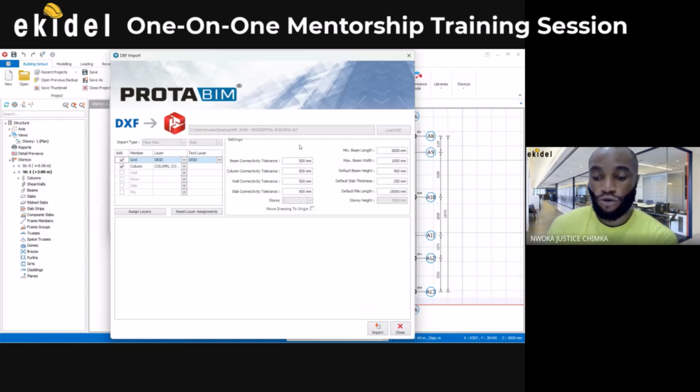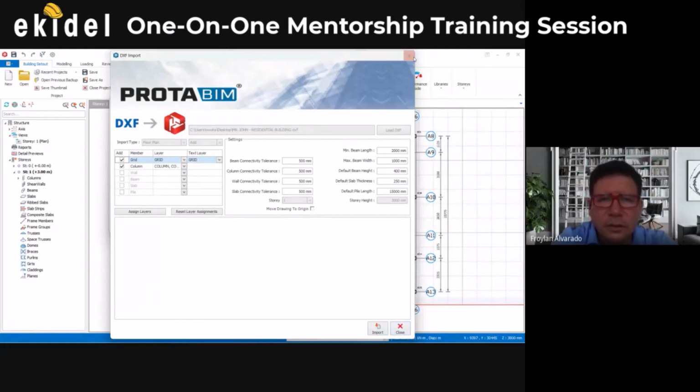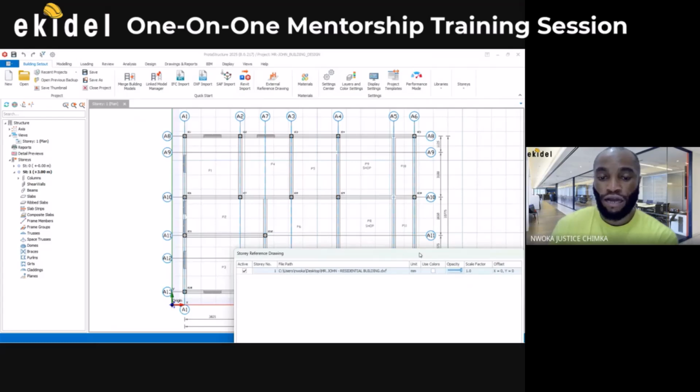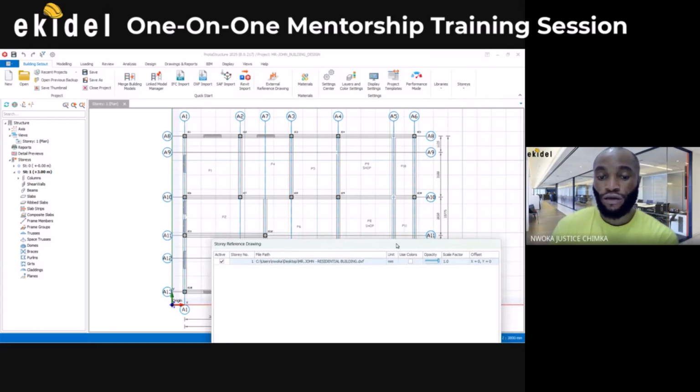Once you have done that and clicked on import, to be sure that the process is done, I'll just show the print log. Once you see that, you can then say close. So I'll just cancel now. Now you can see that we have our grid lines showing, and then we have our columns.